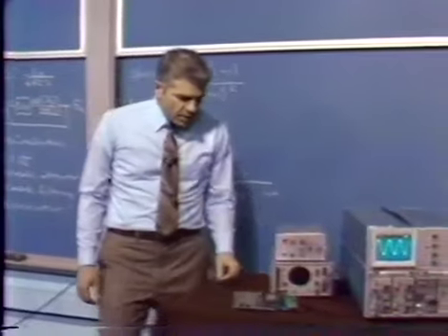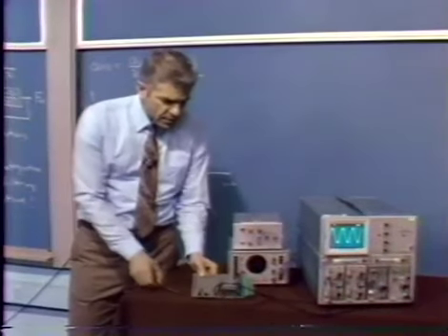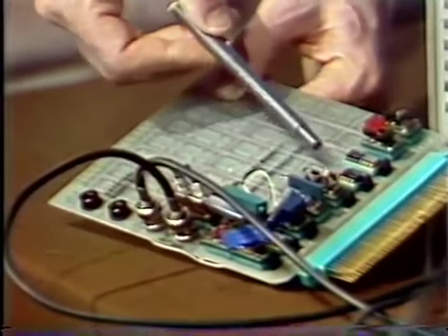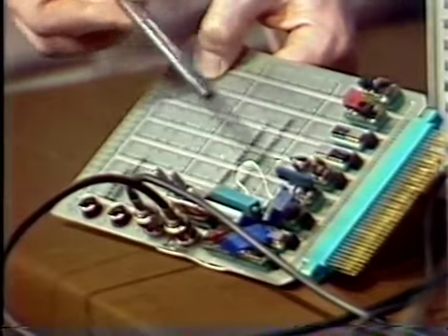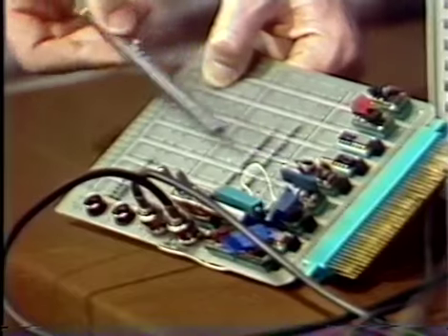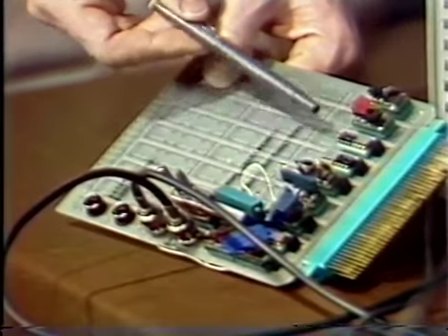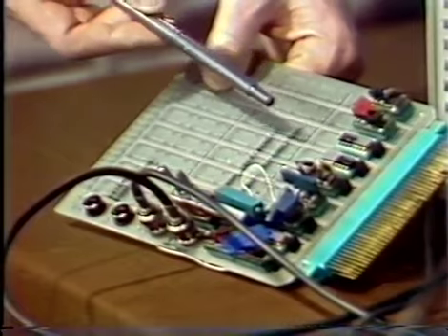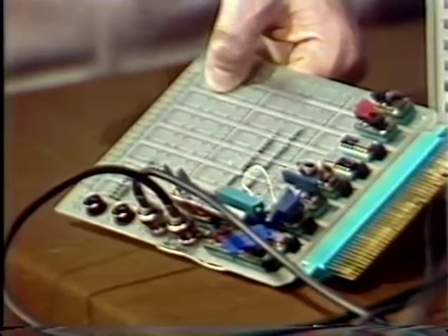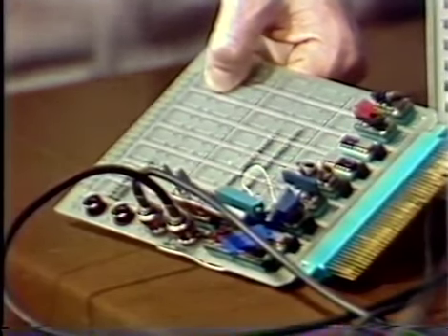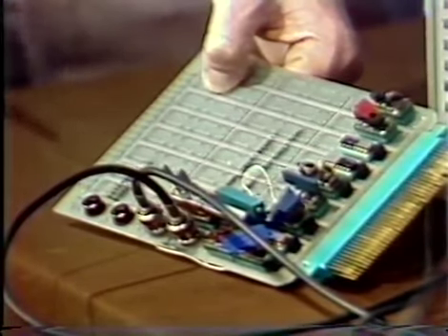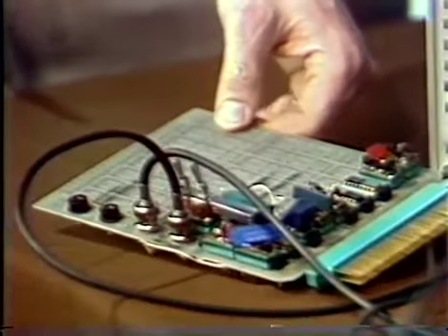And here we have the experimental system that does this. There's a collection of operational amplifiers, and I won't go through all the details of that, but there are a number of operational amplifiers. The two basic ones doing our quadrature loop. There is another operational amplifier that really mechanizes A of S, and then there's several more that do the rather sophisticated envelope detection, a very low ripple type of envelope detector, multi-phase sort of envelope detector. So that's what the collection of operational amplifiers is used for.